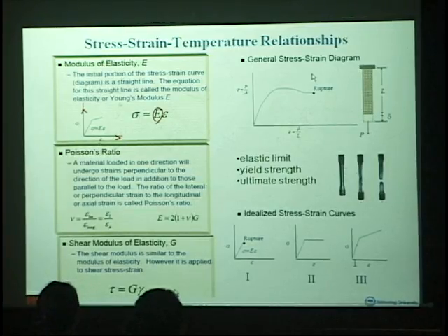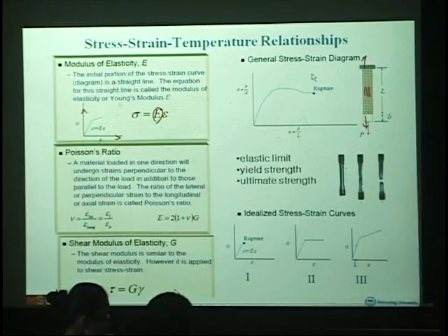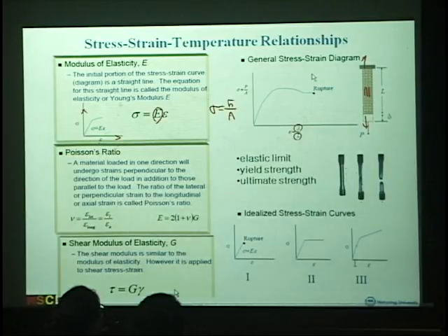We attach a strain gauge here, and then we apply the force, and force divided by A is defined as stress, and deformation delta divided by L is epsilon. And this is usually defined as the Young's modulus. In a real material, up to here is just the linear range. So stress is defined as E times epsilon.